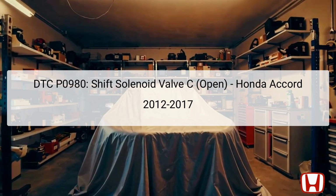The DTC, categorized as Shift Solenoid Valve C, open, reflects an issue primarily related to the vehicle's electrical circuit, not mechanical components. It's important to know that this DTC triggers a fail-safe function, preventing the transmission from shifting into second or fifth gears. Consequently, vehicle performance is affected, impacting acceleration and overall drivability.